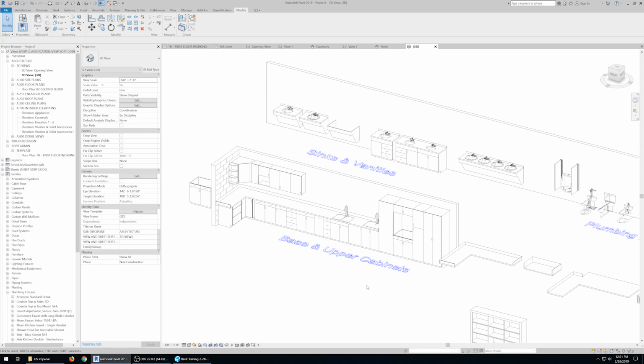It is advanced. So a shared parameter is a parameter that you create that your project environment has no clue it even exists. So you've created a parameter inside your family, but your project environment goes, I don't know what that is. And a lot of times when you click on it, it'll have a little question mark.